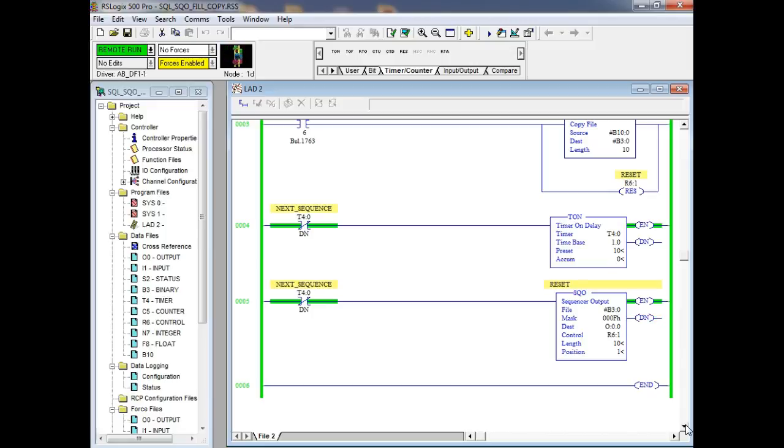So what I'm going to do is strip off these other 2 nibbles. These other 3 nibbles, I'm sorry. Then we're going to output this out to output 0, word 0. I'm using R6 for the control register for this. I'm going to go length, and right now it's on position 1. Of course, my motor's not doing anything because I've got nothing in the table.